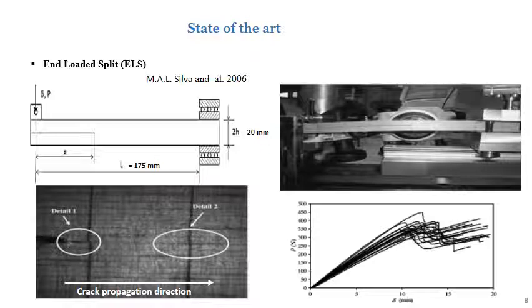Mechanical testing was performed in a universal screw testing machine, Instron 1125. The ELS testing machine included a linear guide system allowing horizontal movement of the collet translation during loading. The tests were carried out in displacement control mode with a crosshead speed of 5 mm per minute. Two sheets of Teflon film were also inserted between the initial crack surfaces to minimize the effects of friction. During the tests, the applied load and displacement values were recorded.